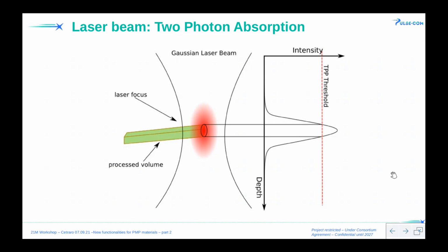However, using this kind of setup, we can go much lower than what's theoretically possible for the central wavelength. The trick is that, of course, we have to use a Gaussian beam, and this is the primary reason I've shown the Gaussian intensity distribution. We know that for a specific photoresist, there is a certain energy density, a threshold level, above which two-photon absorption becomes predominant.